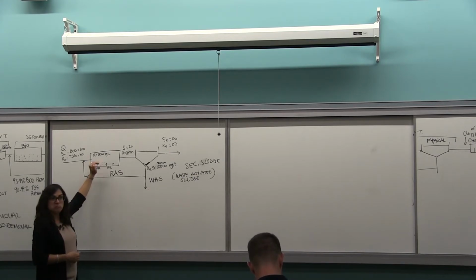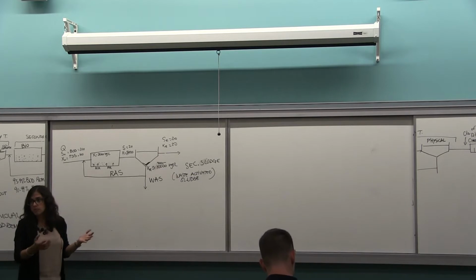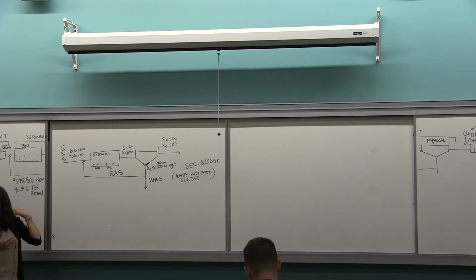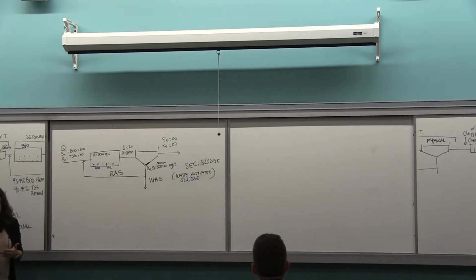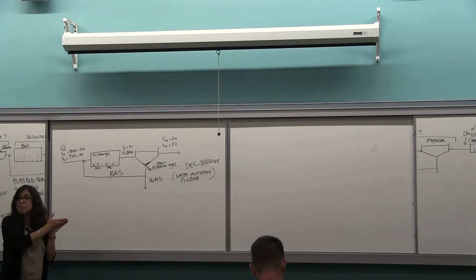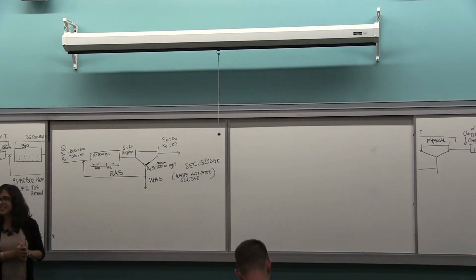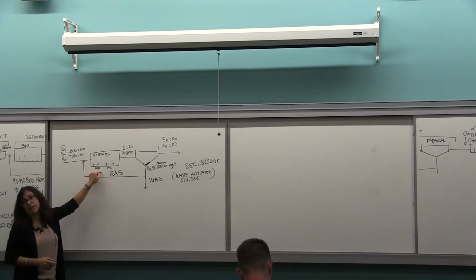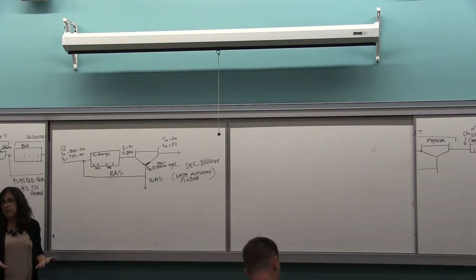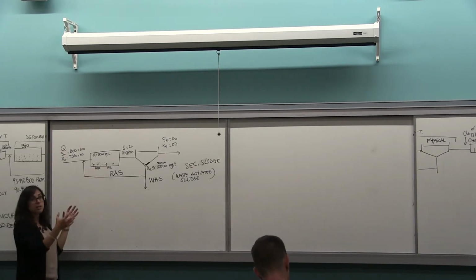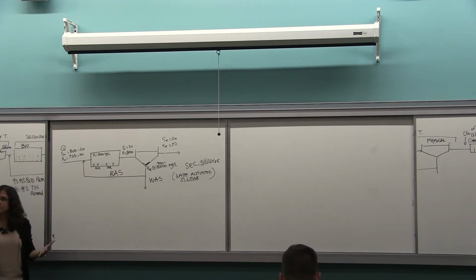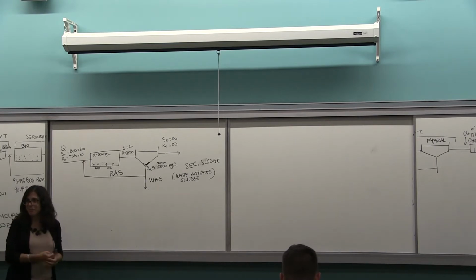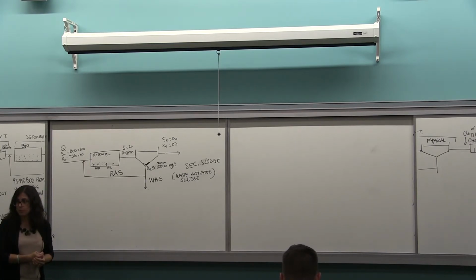So it's just all different types of microorganisms in there that will eat that BOD. All right? It's the same process that happens in the river. The difference is that we add air. So we speed up the process by providing enough air, and we speed it up because we are concentrating bugs in there. Instead of having millions, we have trillions of bugs in there to do the process.